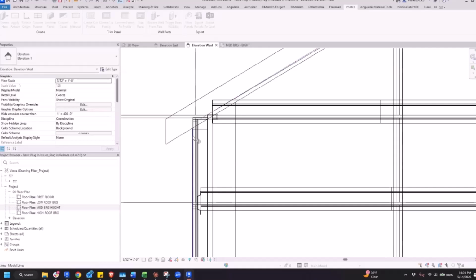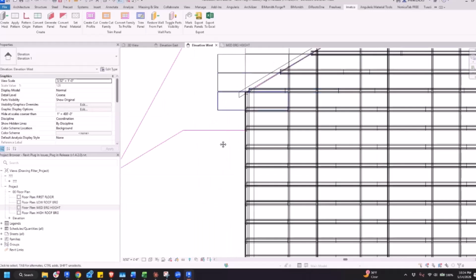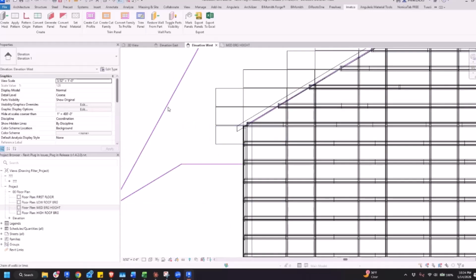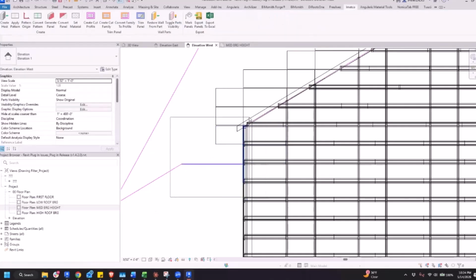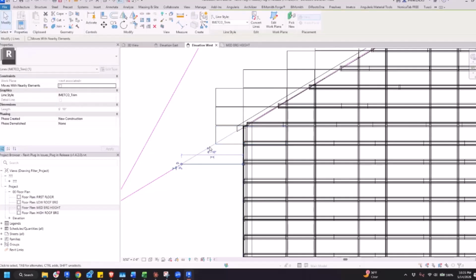All right, now you finish the sketch. Now you go to the second step, which is cutting the family. You hit finish, select the lines, hit finish. And this is because the family that we used is a 2022 family, so just don't be too concerned about that update. It should be fine when it's updating. It's updating the generic family, the cuts. And now the cut should work.